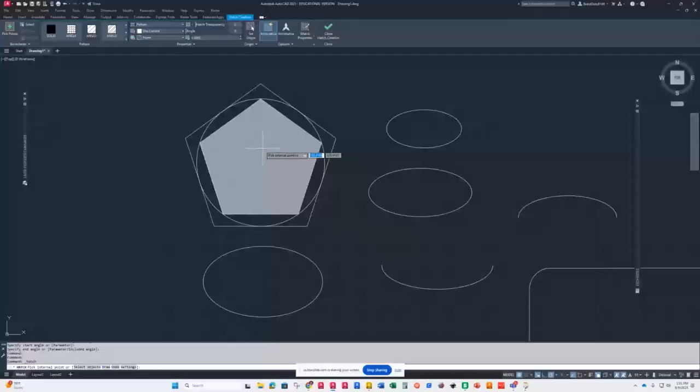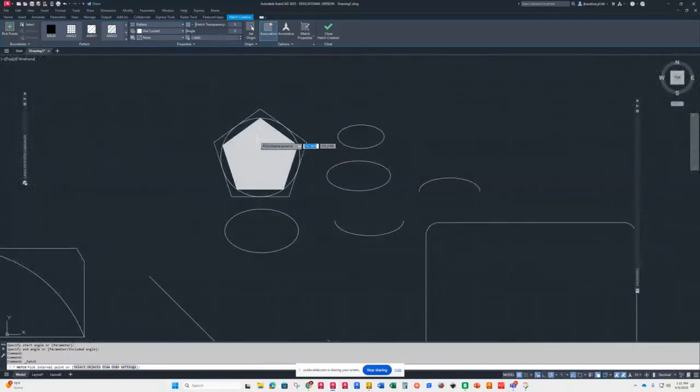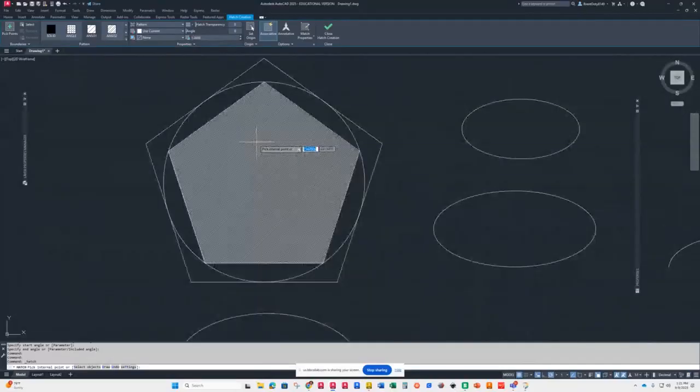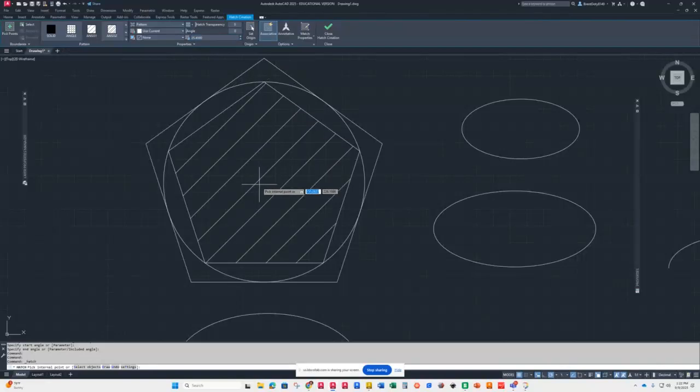And so that must be pretty big because, see, those are actually spaced. So how do I make things bigger? Well, if that was metric, then I would say, oh, I need to turn this into a metric scale, so I need to scale these up. So I can go up here to my scale, and I can change it to 25.4, and now it's a metric size. That would make sense to somebody.